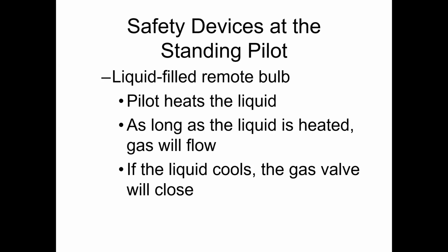For the liquid-filled remote bulbs, the biggest thing to understand is that they will build up soot on them just like a thermocouple. All right. And if it's got liquid inside of it, that soot acts the same exact way it does with the thermocouple. It's going to be an insulator.